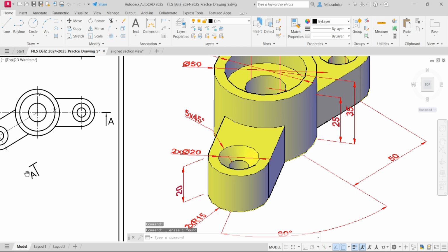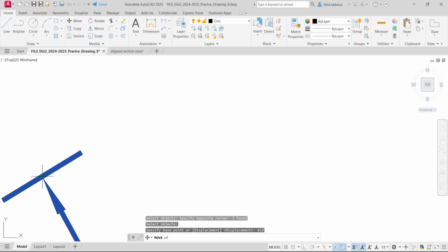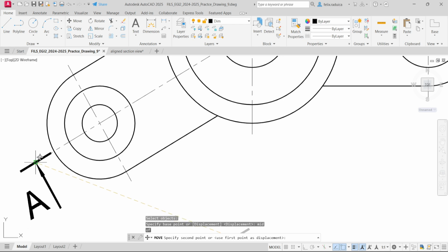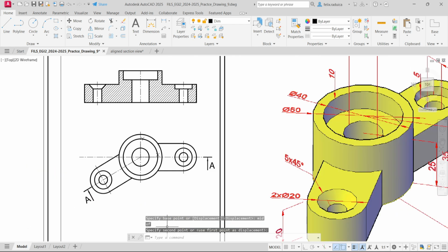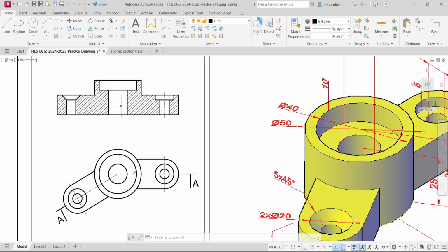We can do it like that, and then move the newly created symbol by its midpoint here to the designated point, which is here. Now we have these two that designate our mixed dash dotted line that is supposed to be the cutting plane. And now here we have to label this.